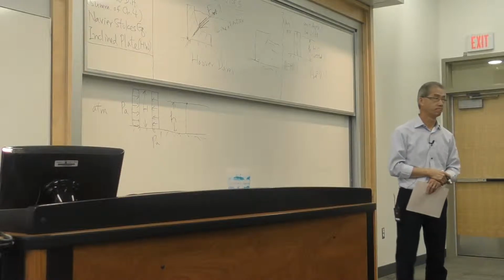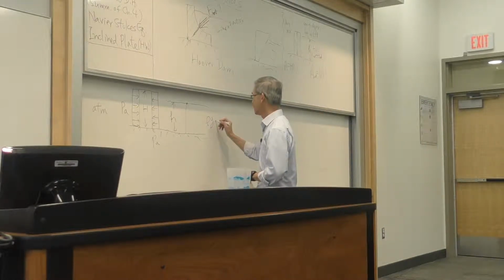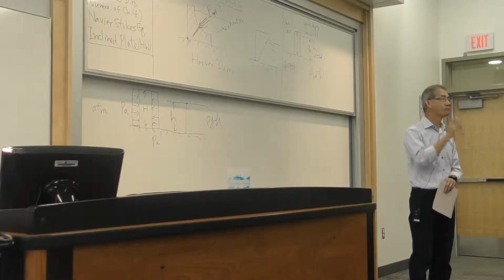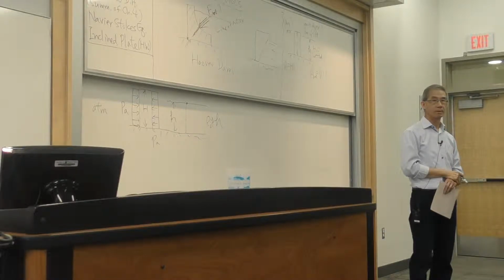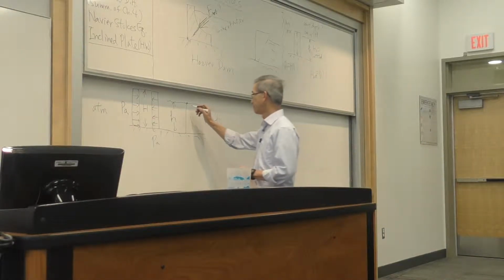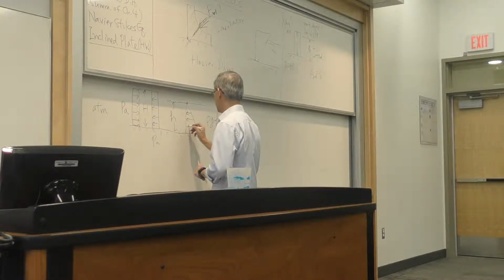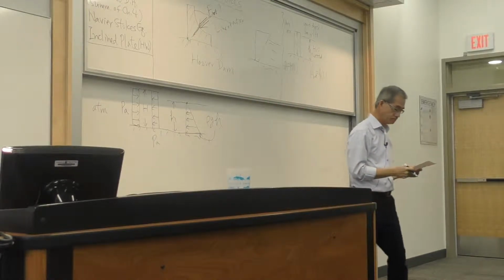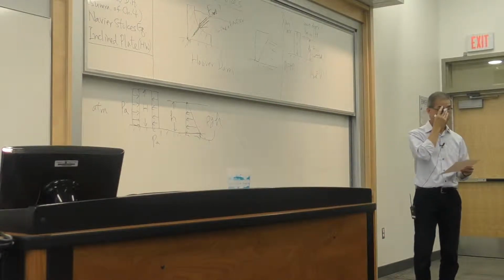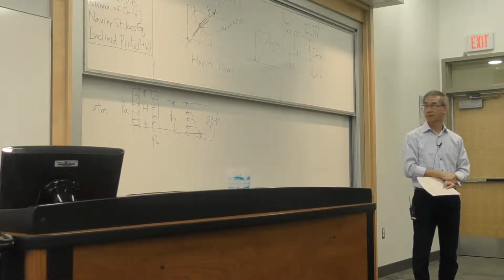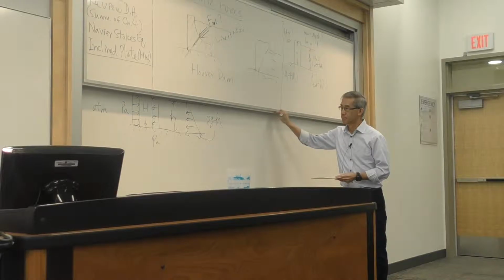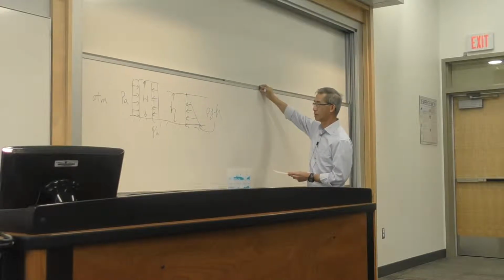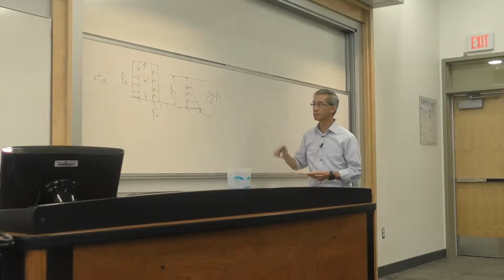Rho gh. Rho gh. And what distribution? What does the profile of the pressure look like from top to bottom? It's linear, a triangle, of which the base is rho gh. Let me stop and make sure you understand how it comes about. Any questions? Is that clear? Okay? So far, so good.